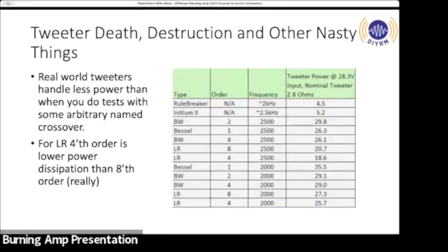When you buy a dome tweeter, very often that spec sheet says, this is a 100-watt dome tweeter. No, it is not. Okay? If you put 100 watts into that tweeter, it will launch on fire faster than you can hit the volume control. Okay? I have done this.